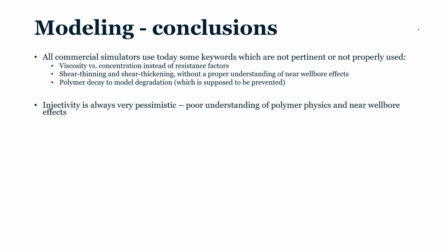You have to find a way, instead of studying polymer degradation, to minimize it. You can input something in simulation just for assessing variability. But in the end, if you have so many parameters, how do you know which one you will change? Will it be retention, RF, RRF, clay lithology, polymer adsorption? So we don't really know. Salinity, mixing parameters, the gamma factor, these kind of things, we don't know. So my point is, it would be much easier to take few parameters which make physical sense and to use them.